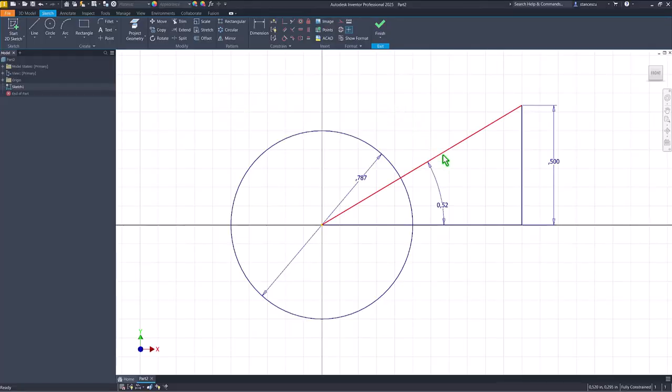Let's change the color of this sloped line. We go to Format, we select Default, and we apply green, for instance. This line is green. Now the problem is that if you want to try another line, this one, the color is also green. Ctrl Z. We understand that this color change is permanent, so we have to select Default again if we want to use the normal color.